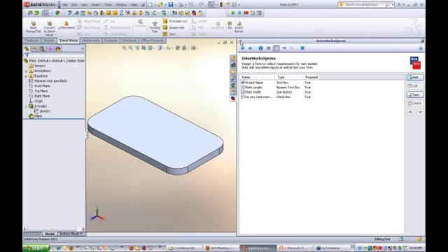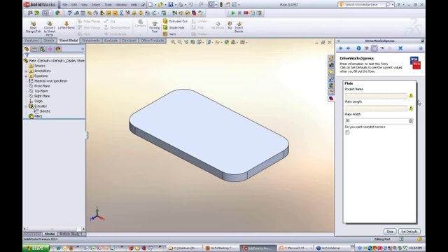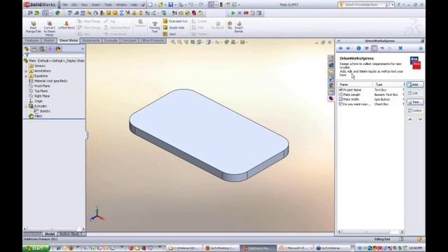Okay. Now we can test that at any stage. So I'll just make it a bit smaller, so it looks more like it will be on the screen. Simply click on the test button, and that's how my form will look. It's project name, plate length. So if I type in 500, it won't like it. Type in 200, it likes it, and so on. Tick box. Okay. So we've captured the data, we've created the form for data input. We need to link them together now with the rules.